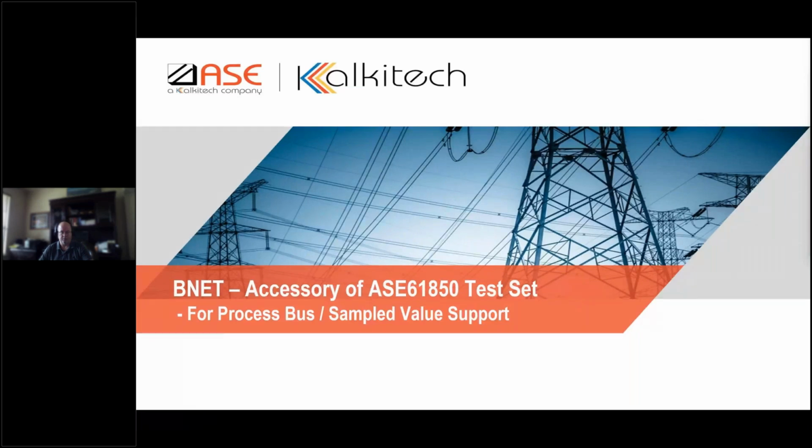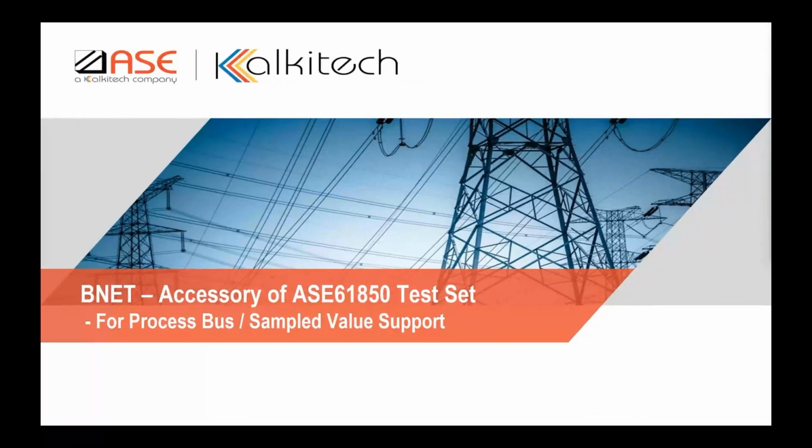So here, by process bus, we mean the communication from the CT/PT, like current transformer, voltage transformer, and all, to the relay. That part has been digitized, and there will be a separate network that connects from this CT/PT to the relays. We refer to that network as the process bus. All right, okay, got it.